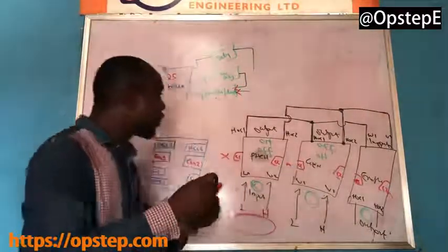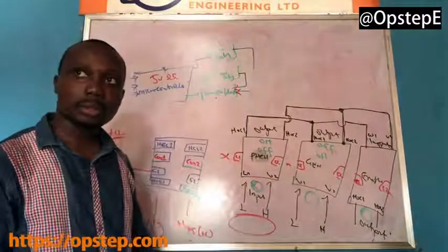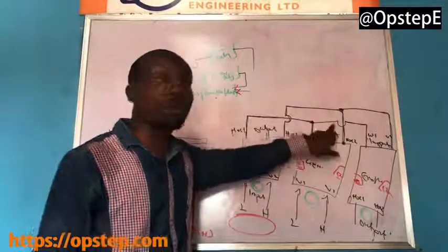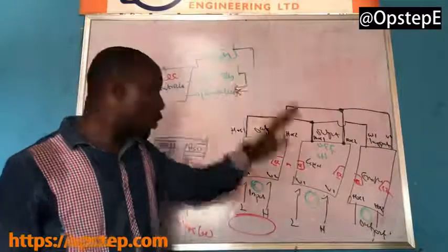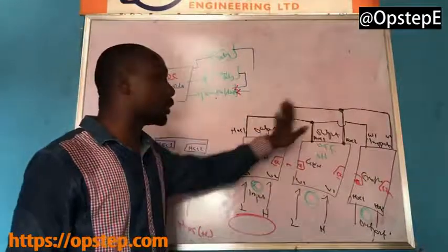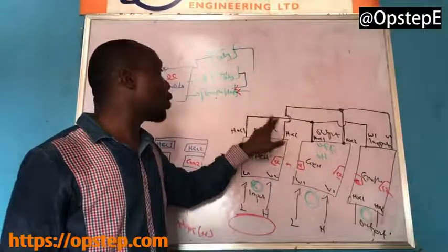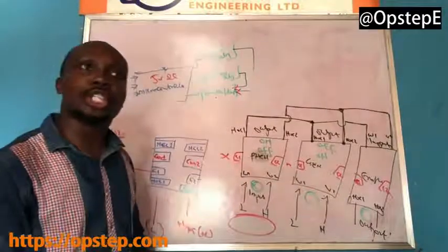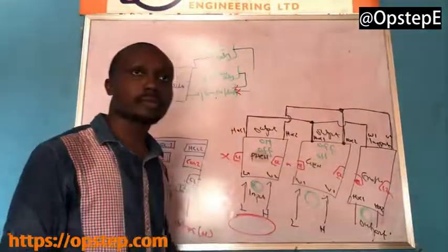But because their normally open contacts are bridged, whether you put one here on the normally open contact and put the other on your normally open contact, whether it is NEPA, the two will come on. Whether it is generator, the two will come on because they are connected. So we cannot take the indicator from the normally open contact. So what we did was we took the indicator from the what? Coil contact.